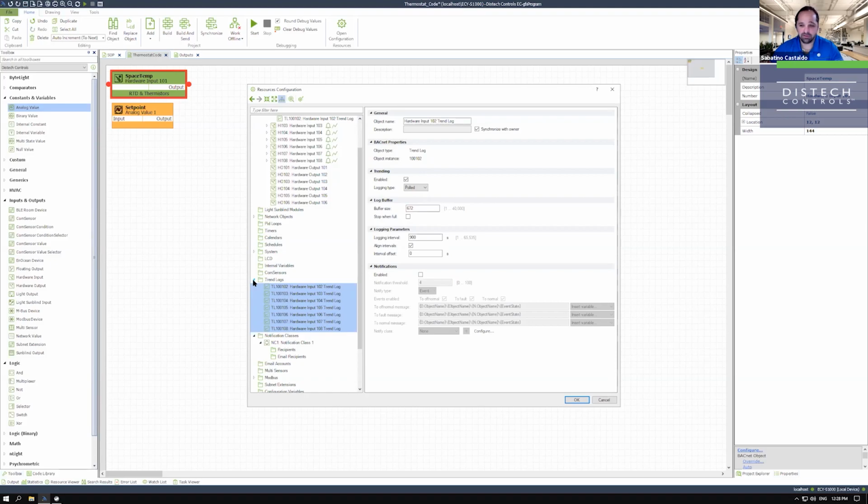So 50 points, you're looking at probably 5,000 records per point to get the 250,000 limit. And 5,000 records divided by your time base, you get to decide how much you want and how much time you want to hold on the controller.